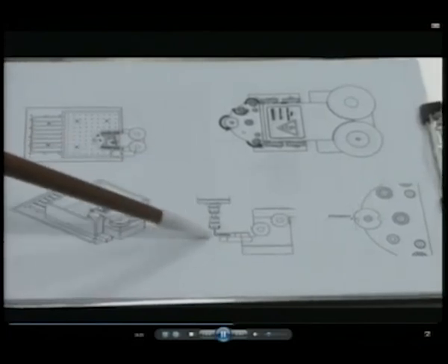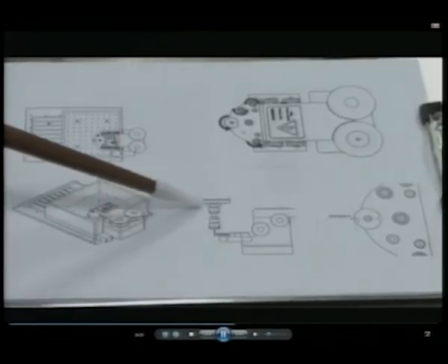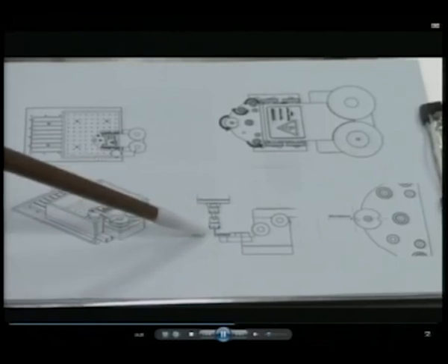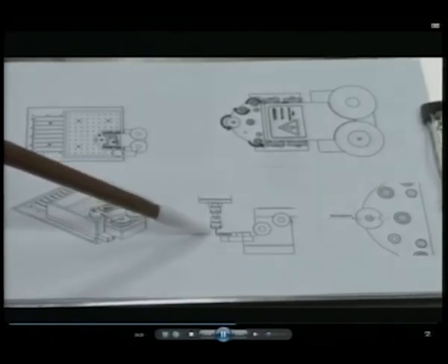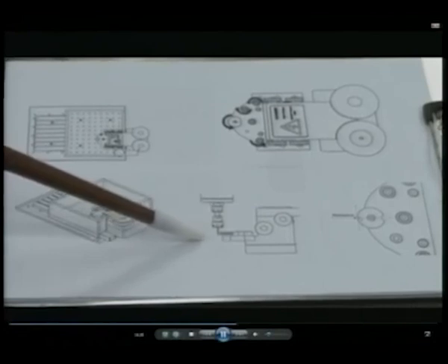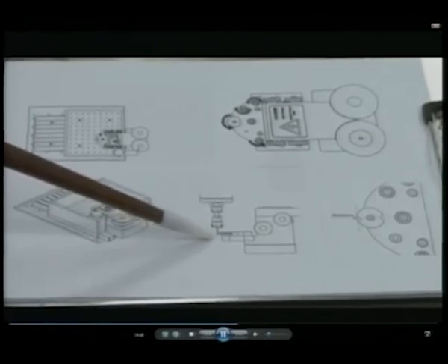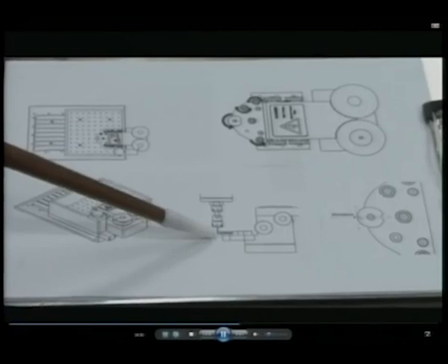The tool, which is now the workpiece, is fixed on the spindle and rotated. Now the objective of the process is to reduce the diameter of the tool. To reduce the diameter, the tool comes in contact with the wire electrically. Same as the EDM process, the tool material is removed and thus the tool is turned to a specific diameter. Through this process, a tool diameter as small as 2 micrometer can be generated.